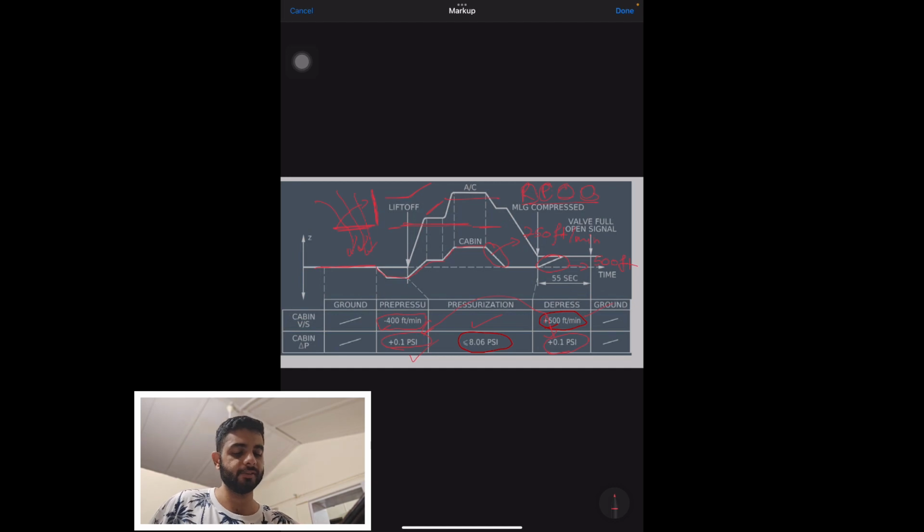So what it does is it says okay, the outflow valve is in manual mode, it's not opened by the pilot, I'll open it. Okay, so it depressurizes the aircraft in case of 4 conditions that must be satisfied. So what are these 4 conditions?